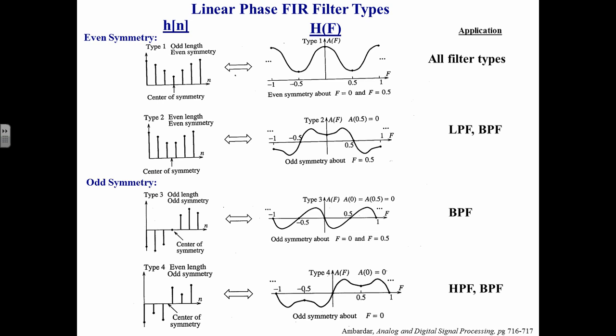And this comes about because of the way the discrete time Fourier transform works, where certain symmetries that show up in the time domain infer and produce other kinds of symmetries in the frequency domain. And some of those symmetries that must be present in the frequency domain give rise to some shapes of magnitude response that make it either possible or impossible for me to make the particular filter shape I want.